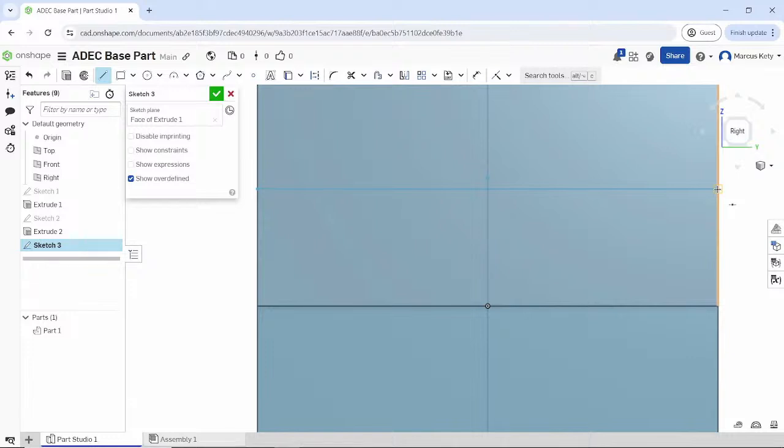I could do a single line, and you can see how it's giving me these options of what it wants. That little symbol right next to me is the midpoint symbol versus the coincident symbol. So here it's anywhere along the line, but midpoint means that it's exactly the midpoint of that line, and that's what I want. I can hit escape, or when I draw this line the first time, I click, and then I'm going to double click instead, and it doesn't drag off of that original point. So I don't have to hit escape. I can just double click.